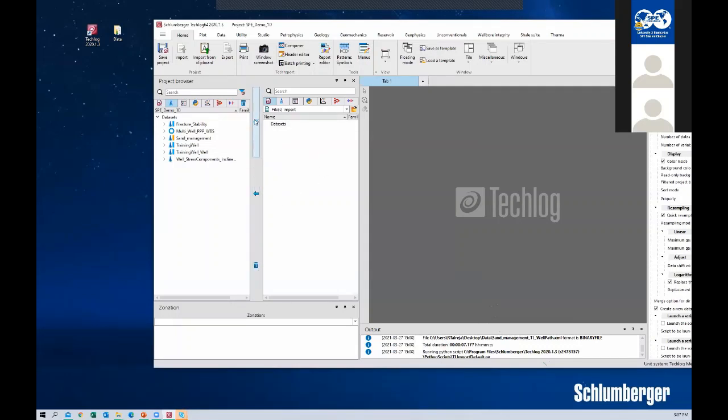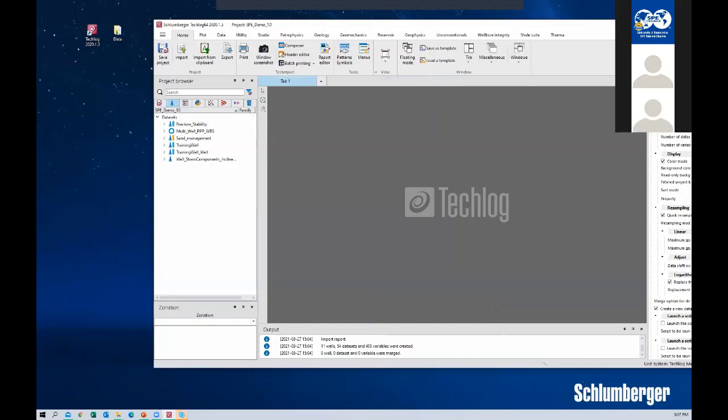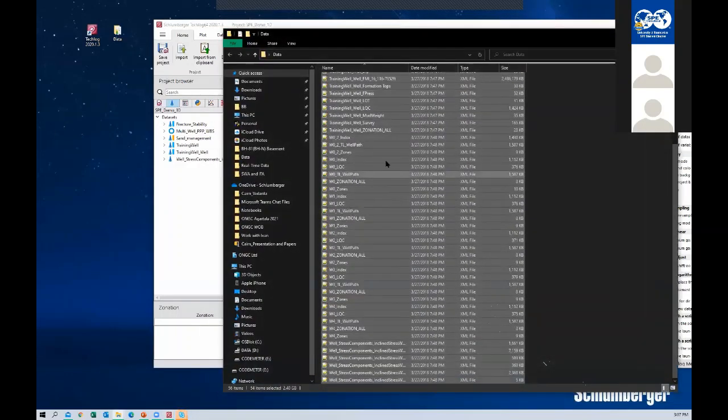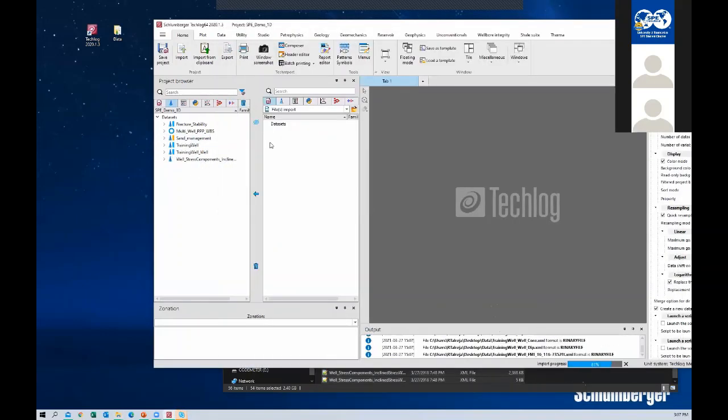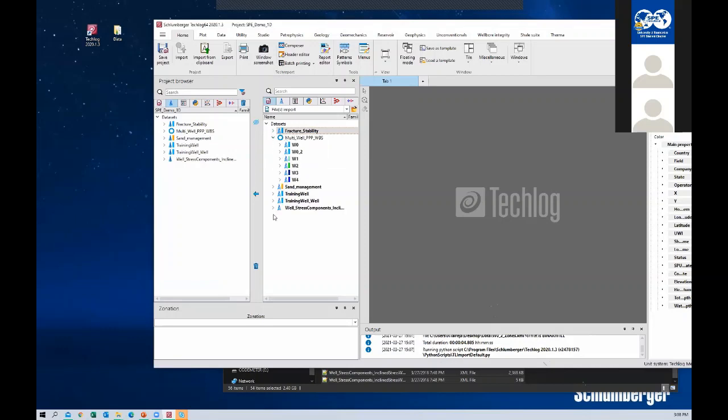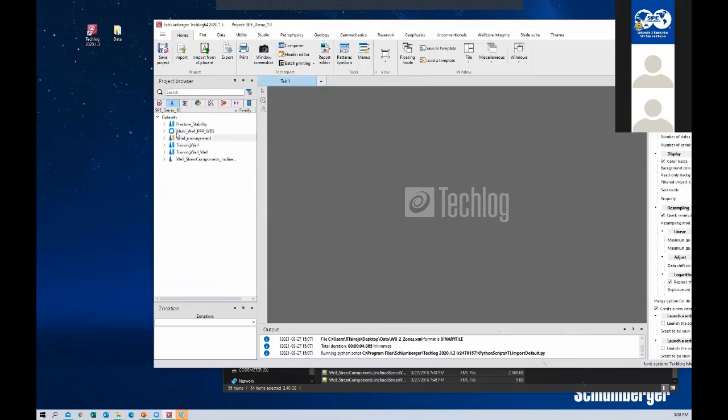But I guess everybody wants to do it quickly, and the quickest way of loading the data is to select the well, select all the data set, and just drag and drop like I did again, right? It will identify by itself what wells it has, what data set it has, whether it's image data or log data, and it will show you. You load the required data set into your project, right? And we are done with the data loading part.